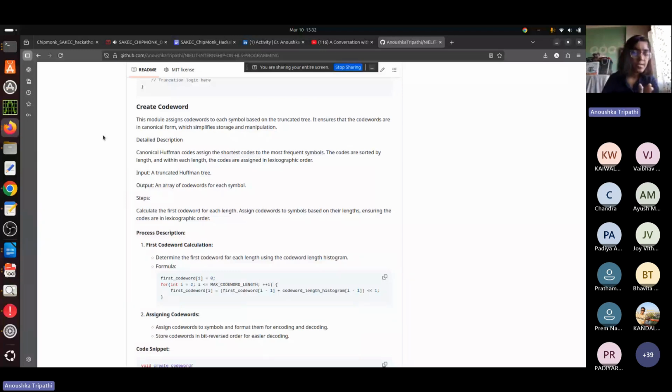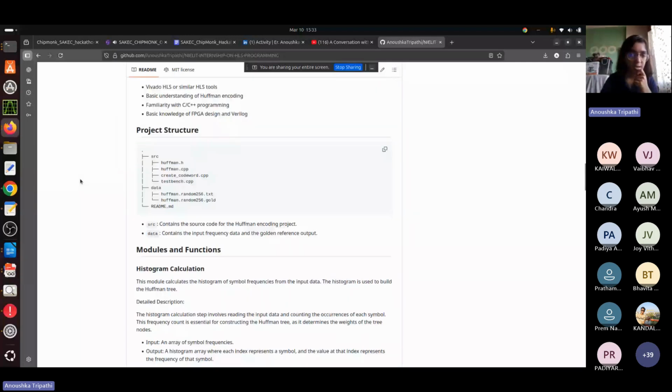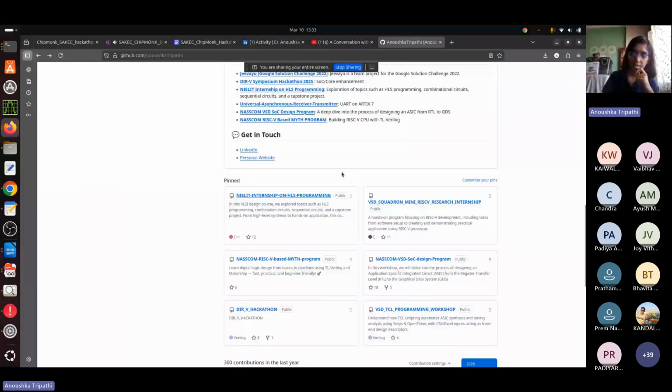And yes, if you don't have any FPGA, no issues. If you don't have Altera or Xilinx, you can also try some Lattice FPGA, because it uses an open source FPGA toolchain. And if you have no such FPGA or anything, you can use GTKWave and iVerilog for simulation, and you can create some simulation from that also. That also works. And you have to put the screenshots also of your simulation.